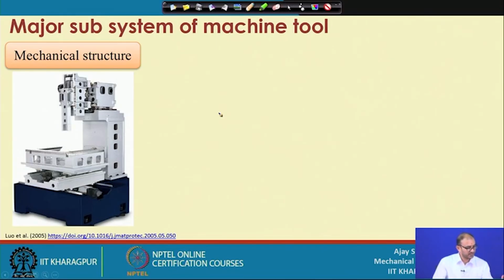So, this is the z axis. In this z axis what will you mount? You will mount a spindle axis and then you put tools and many things on top of it. In this particular box, in this axis you are putting a y axis, in this line you are putting an x axis. Once these things are over, you have to install motors and everything to run these particular things. You need one sliding axis for the movement of the z axis up and down also. You have to mount a spindle so that it can rotate.